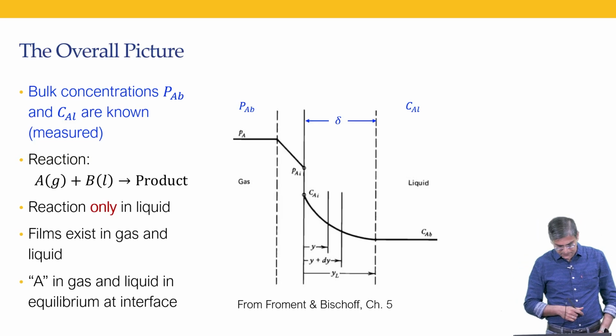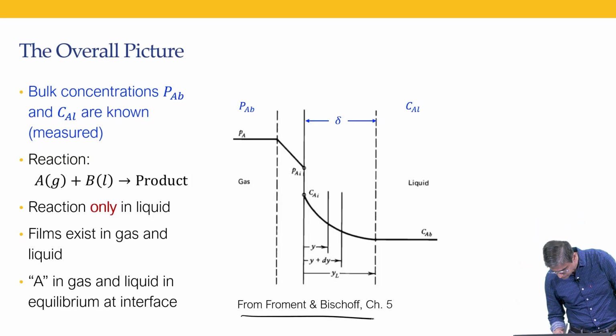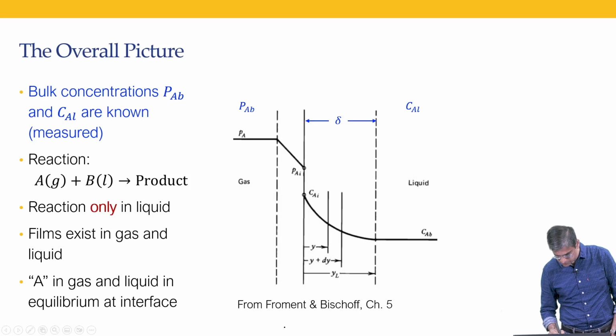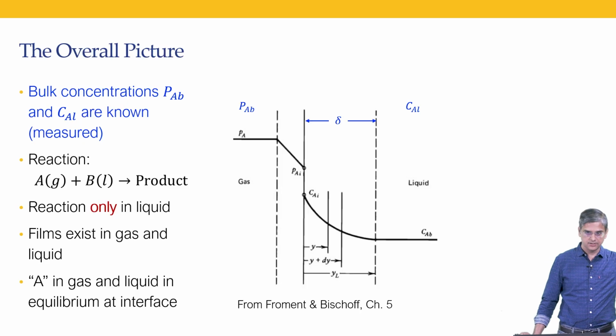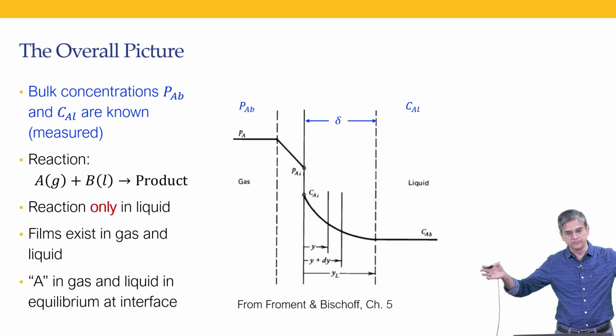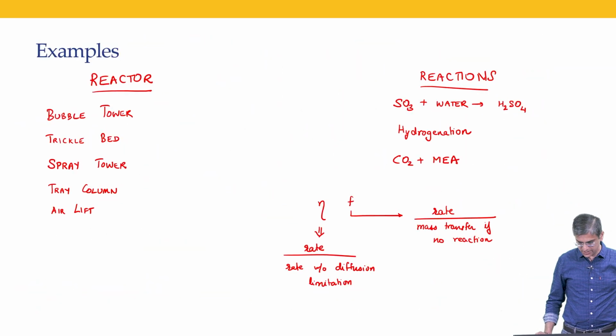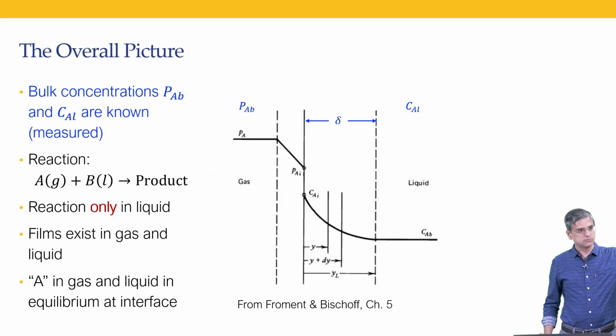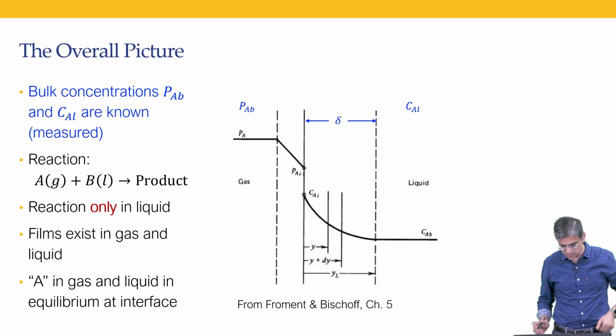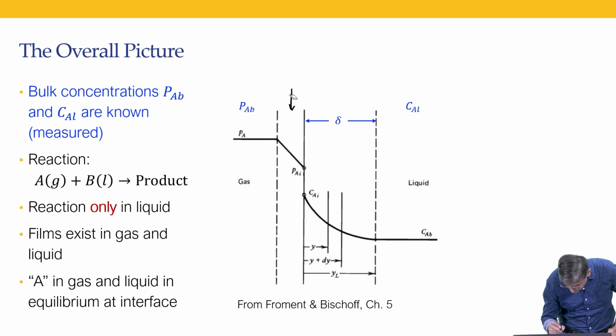Okay. So from Froment and Bischoff, this is the overall situation when it comes to our gas film and liquid film. Very similar to what I had shown over here. In your gas film, there is no reaction, there is only mass transfer, and therefore that particular mass transfer is going to be governed by, as we have always done,